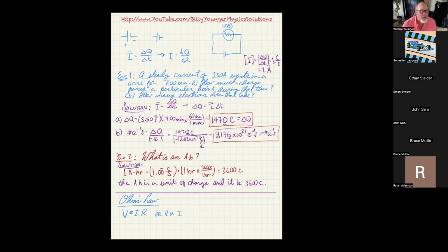And that's true. What it says is, hey, if I take an object and I put a voltage of 10 volts across it, then I'll get a certain current, let's say 1 amp. If I now take that same object and put, instead of 10 volts across it, I put 20 volts across it, then now I'm going to get 2 amps. And if I put 30 volts across it, I'm going to get 3 amps, so on and so forth. That's really what it says in that proportional form.